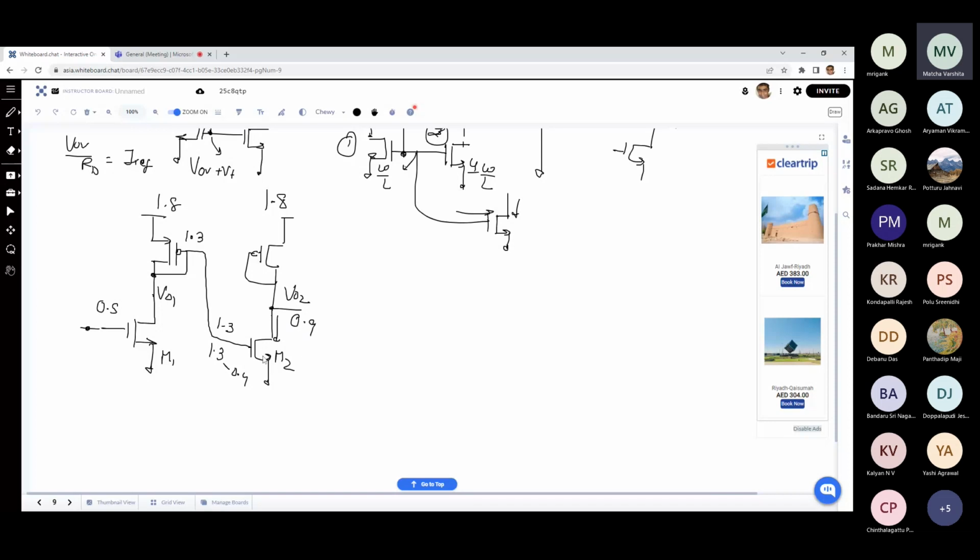Second thing is this bias current is going to be huge. As compared to 0.1 overdrive, here you are providing a huge overdrive, so that will unnecessarily waste a lot of current in this stage. That current is not desirable. Why is it happening? Because whatever 0.1 VGS overdrive you provided for the NMOS over here created a corresponding V overdrive for the PMOS. Now this gate voltage is suitable for biasing another PMOS stage, but you are applying it to the NMOS, and that is producing a huge V overdrive, right?